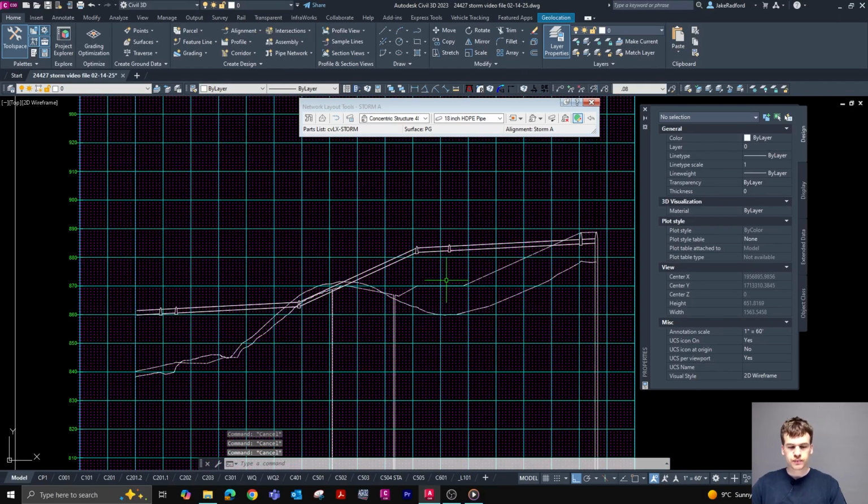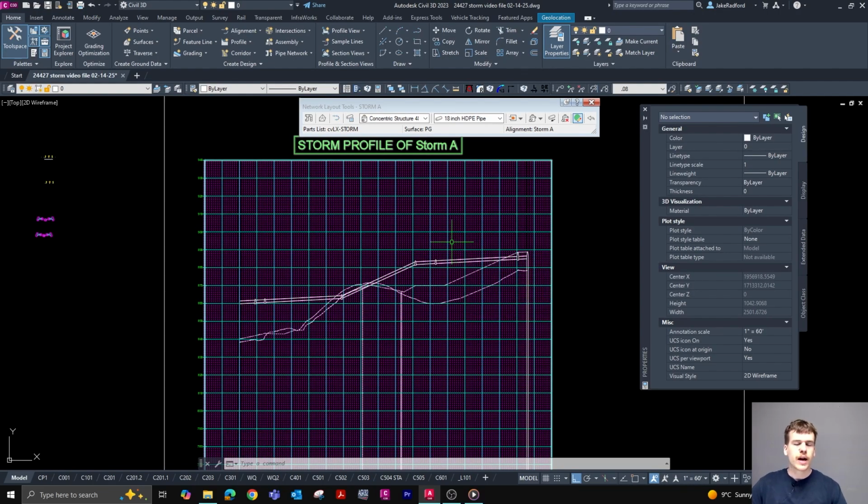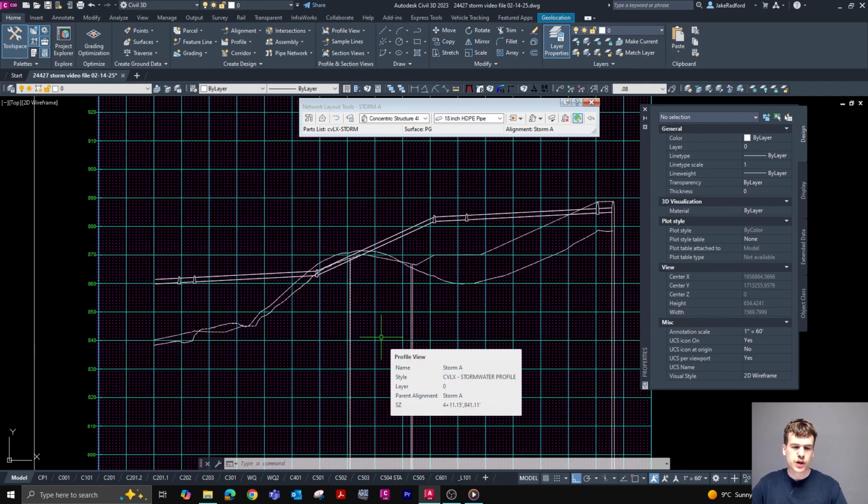So typically, what I usually prefer to do is do exactly what we just did. I'll just punch in an elevation at one point on the pipe that seems to make sense, run it at 1% from there, and then I'll generate my profiles and then continue to iteratively design based off of the constraints, one of the primary constraints being enough cover. So there are going to be areas where we're not going to have enough cover.